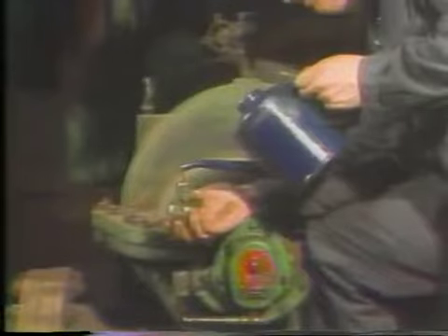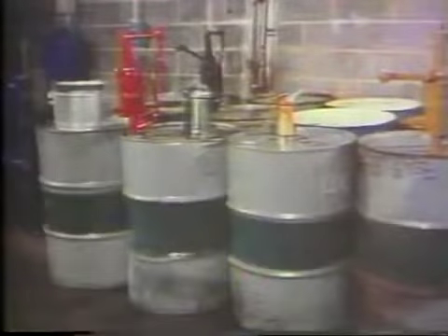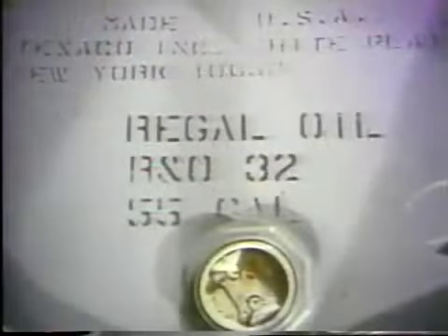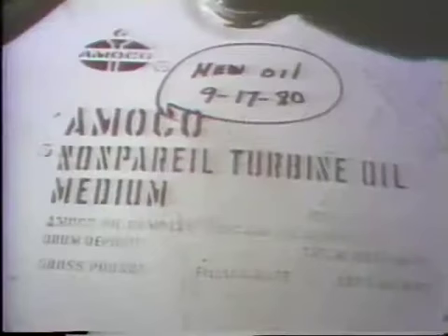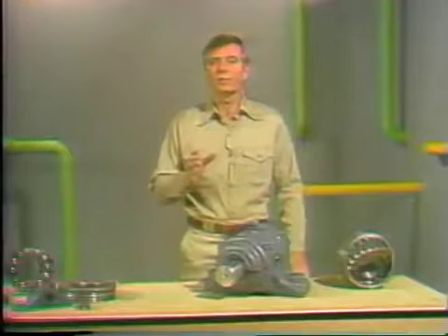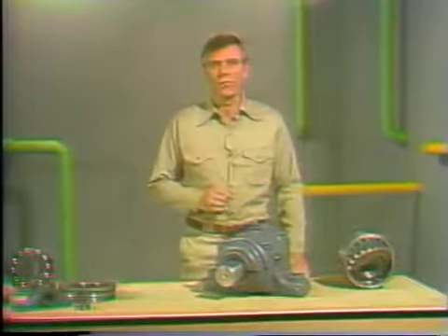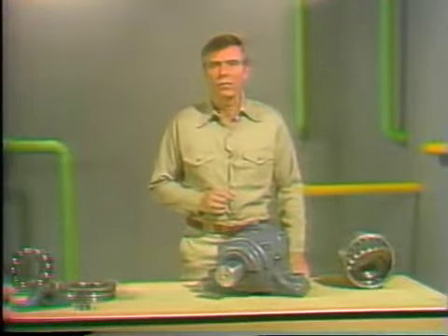You'll need to know which lubricant is right for which machine, and how much lubricant needs to be added for efficient operation. In order to help you do your job properly, plants have a lubrication identification system. Using the wrong lubricant may seriously damage machinery, so it's a good idea to check the manufacturer's recommendations or plant procedures before adding lubricants to any system. If you're ever in doubt, ask your supervisor if the lubricant you have chosen is right for the machine you're servicing.